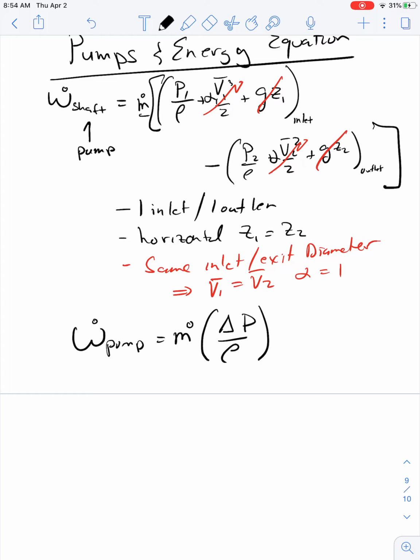And that's the power of the pump that we're looking at. So this is in watts. It's the pump power. Just for a second, if we briefly go back to the figure from the PowerPoint, you can see that really quickly we can determine the pump power from this curve. If we have this red line being our pump curve, and I know I have this pressure drop and this flow rate here, then I can calculate the power here.